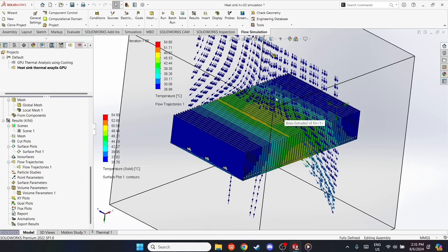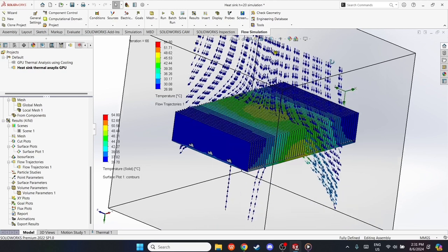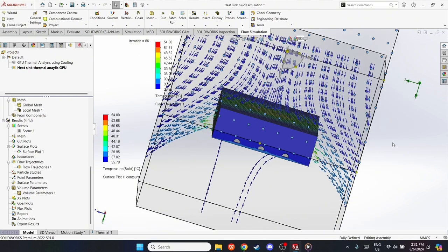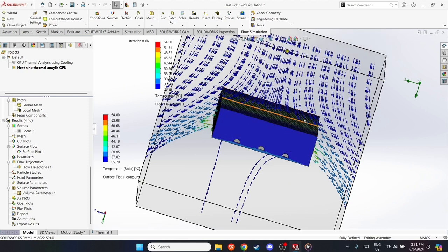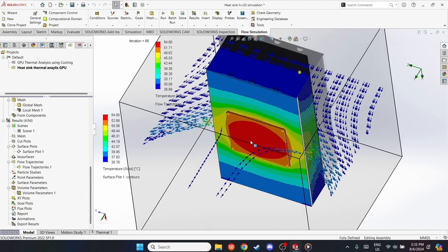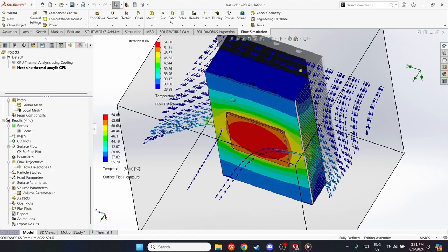While the heatsink is made of aluminium, which has slightly lower thermal conductivity. For the boundary conditions of this simulation, we mimic the real life scenario, in which there is an inlet velocity pointing downwards onto the upper heatsink, so the air flows downwards. There is also a power source directed at the plate at 130 watts.